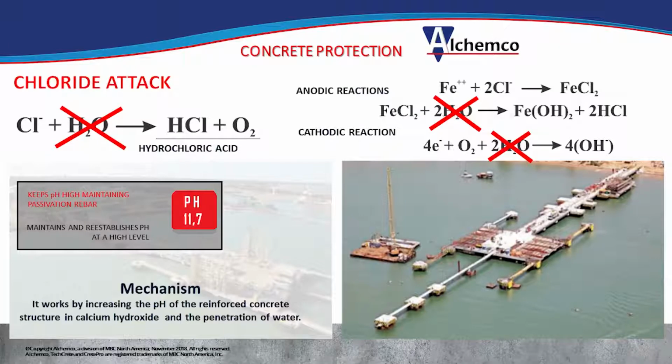So when you go to chlorides, which is always a major concern for DOTs, chlorides, the corrosion, things like that, that's not going to happen either because when these gels form, this barrier is going to block water from penetrating. So you don't have water. And if you don't have water, you're not going to have the corrosion. So from the 4 items that we saw, we were talking about water penetration, the free calcium, the chlorides, and cracks. So this technology is able to waterproof your structure, not only protect, but waterproof.